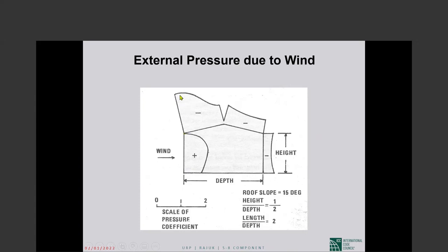And at that corner, look at the suction. Huge suctions develop at that corner of the windward face and the windward roof. And unless the roof is held down sufficiently, the roof is sucked up by the wind. And when that happens, the wall doesn't have lateral support. It comes down. This is the mode of failure that we have seen after every serious wind event.